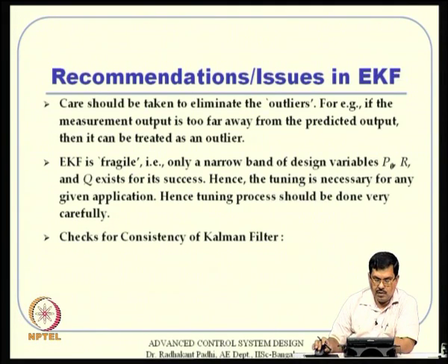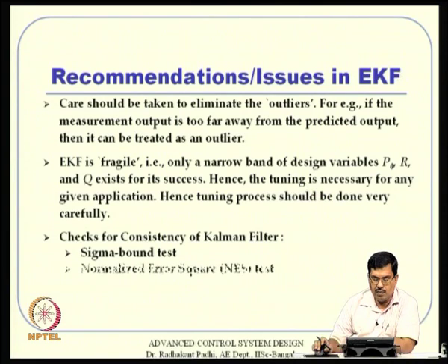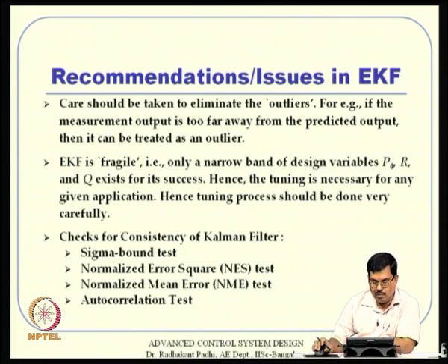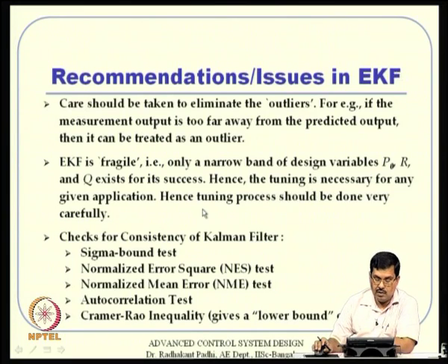And there are consistency checks of the Kalman filters. There are various checks: one is the sigma bound test, the normalized error square test, the normalized mean square test, the autocorrelation test, like the whiteness test, and so on. There are Cramer-Rao inequality tests and so on. So, there are various tests available, and at least a few of them need to be done to have confidence in your estimation. That is certainly recommended, and you need to do that.